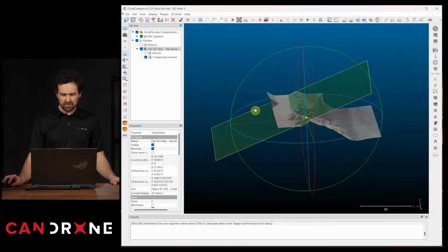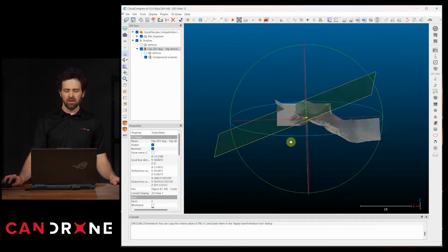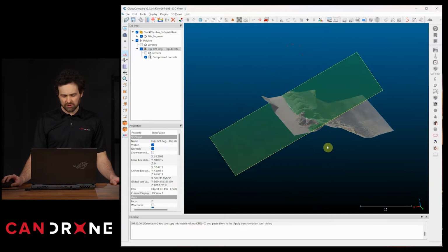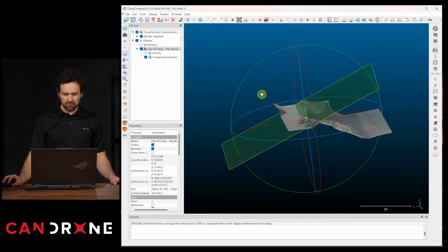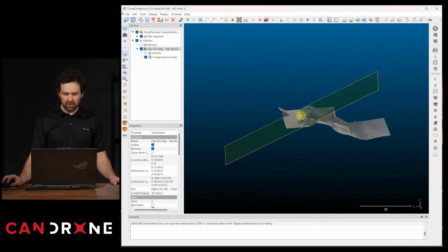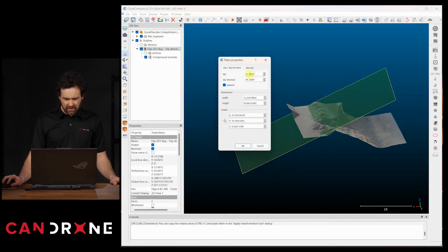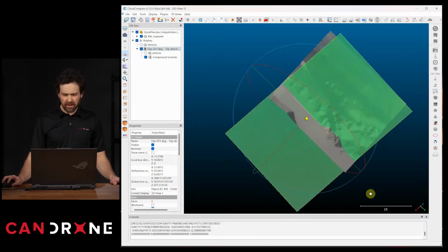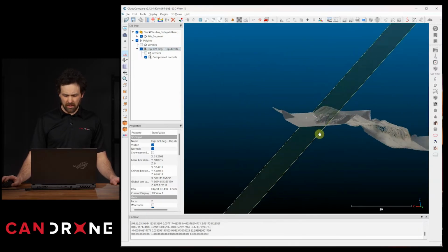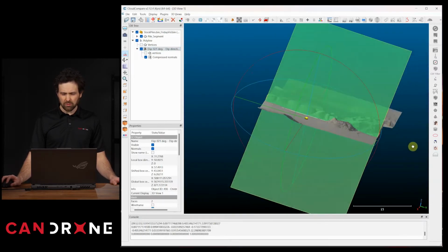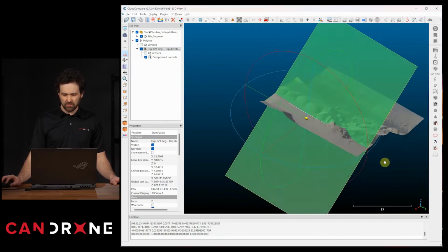Now it's actually orientated the wrong way and it's not sloping to the angle that we're most interested in for preserving the integrity of the road as we excavate this face. So we need to do a few things. First thing I'm going to do is pull open this Edit menu again and see it's only sloped to 21 degrees. I'm going to slope this to 45 degrees. So now it's a much steeper slope, but it's actually turned around. We need to rotate this 180 degrees.